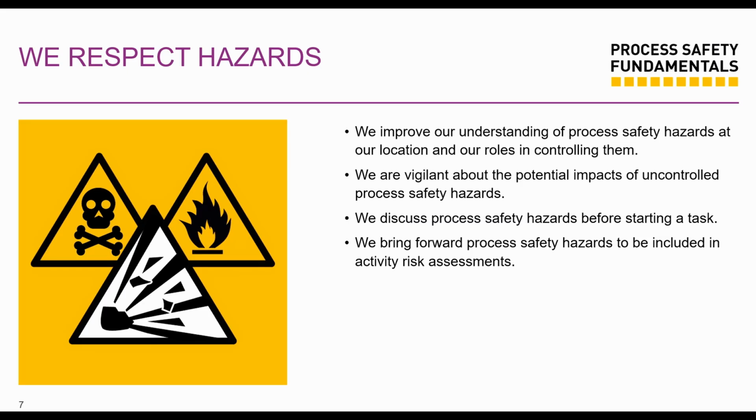Also, another scenario is a vessel that contained hydrogen sulfide. You're having H2S in a vessel, and then you just do a basic ventilation. You open it up, you don't purge it out, you don't try to ensure that you do some gas testing. You don't treat it as a hazardous atmosphere, and you don't do a gas test, and a worker goes into that place and unfortunately succumbs to H2S.